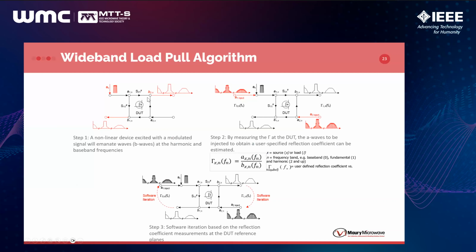What we do is we measure the output signal, and we mimic it through an injection using AWGs, and we condition this signal with different amplitude and phase for different tones. With that, we are able to synthesize an impedance over the bandwidth in the impedance we want.